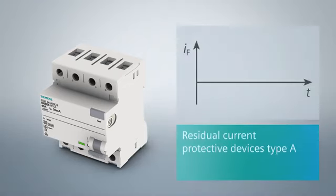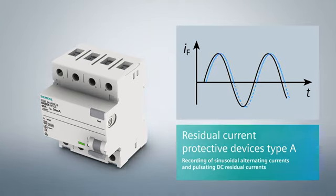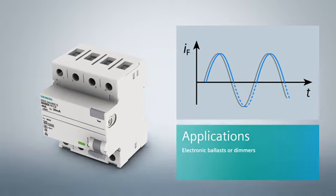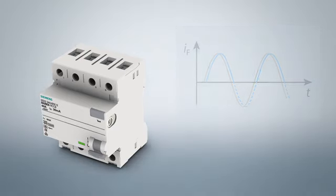In addition to sinusoidal AC fault currents, residual current protective devices of type A also detect pulsating DC fault currents. These devices also control the fault current forms of single-phase consumers with electronic components in the power supply unit, such as electronic ballasts or dimmers. Residual current protective devices type A are suitable for most input circuits of electronic operating equipment.